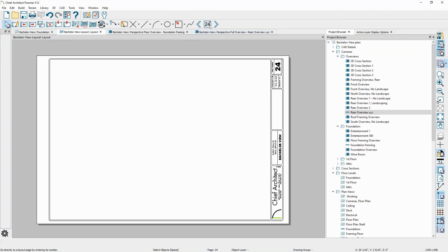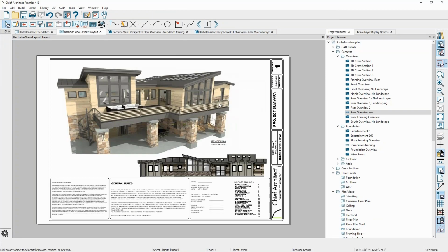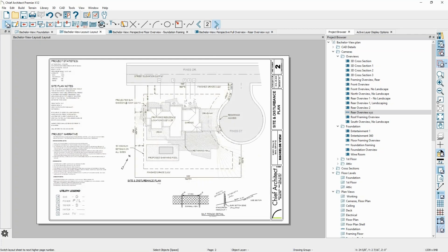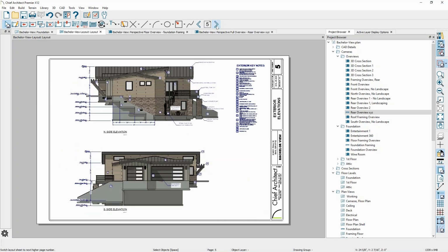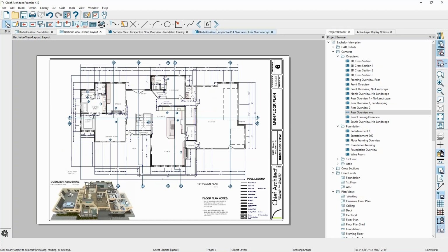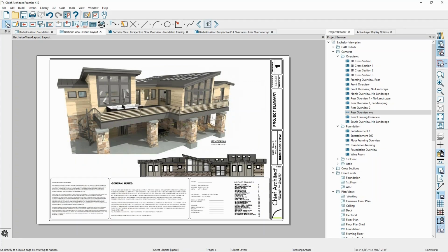I don't like sending my renders to the layout like we just did, because I think the issue that you pointed out is it looks pixelated. The quality isn't so good. I find that you get better quality if you take your image, go File, Export, and then here's the key to that.